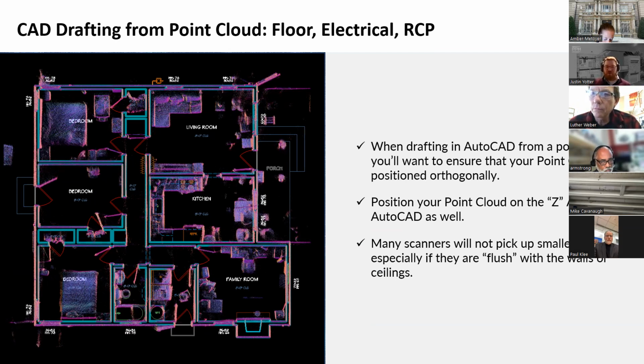If you're going to work on elevations or need to extract any heights from the point cloud, it's also good to position the point cloud in the z-axis. Typically, we start by lining up the finished floor surface of the first floor at 0, 0. And once you have the point cloud well positioned to begin drafting, you should be able to derive all the walls, doors, and door swings, and any other visible architectural and structural information right from the point cloud.